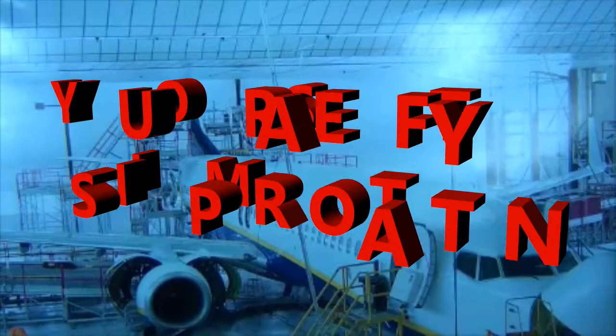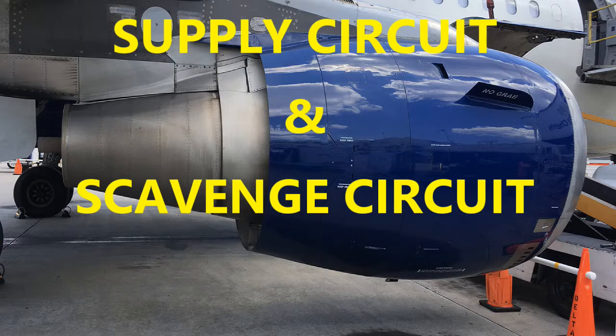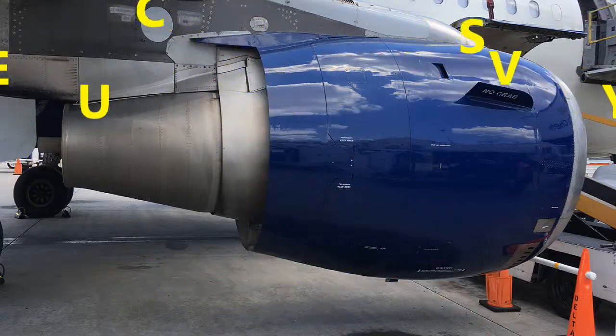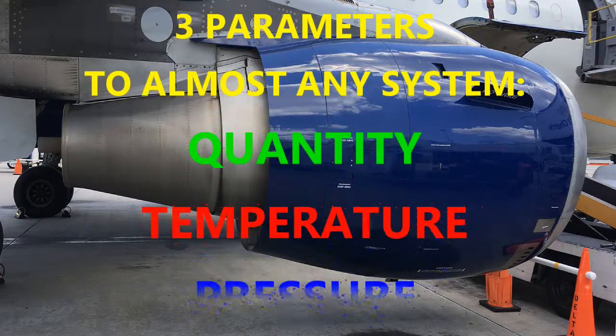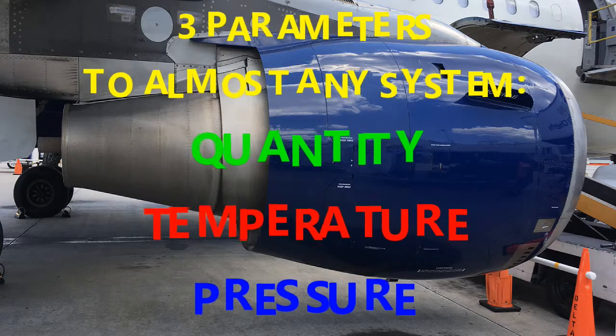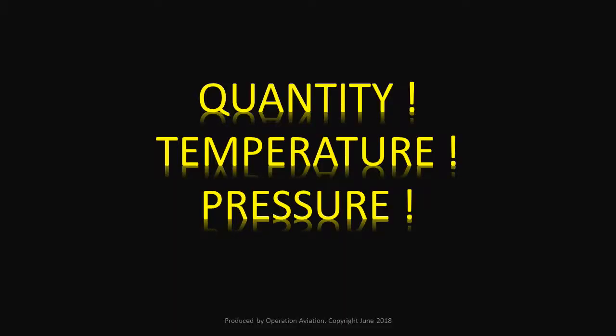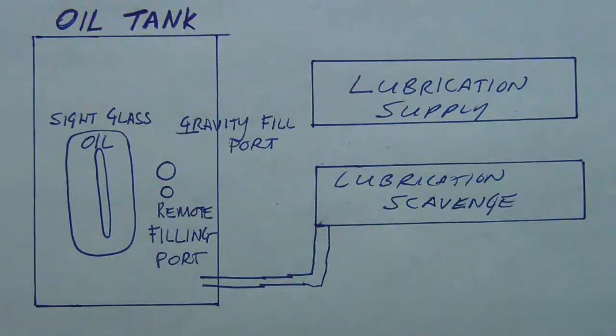You will become familiar with the general concept of the supply circuit and the scavenge circuit, also with the components involved and the locations of them. And I've mentioned this before, I don't know how many times, but 3 aspects to any system is QTP: quantity, temperature, and pressure. All 3 of those aspects come into play in regards to the integrity of the operation that's involved. So we want to make sure that we do have the right quantity of oil as well as the right temperature and pressure at various points. Okay, because we can't really afford to play Russian roulette when it comes to the aircraft and maintenance with it.